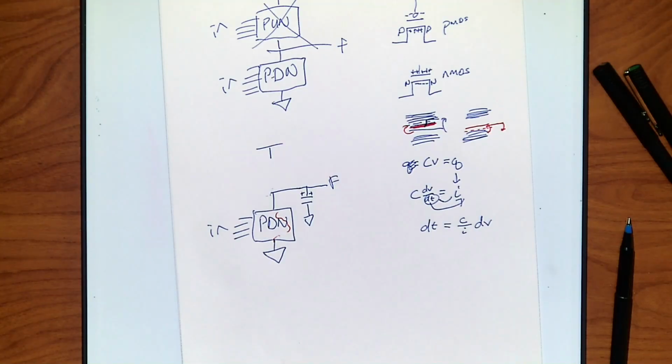So you're just sloshing the charge to another gate, and it'll hold there. There's no real easy drain. You will get some drain, but if you have a path to ground, it'll discharge that tiny capacitor really quickly, and it won't be able to open the next gate.